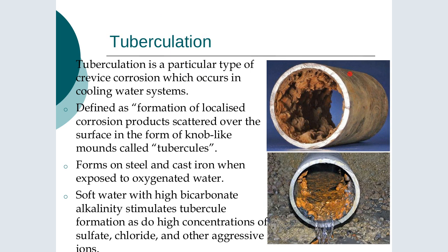So how do we detect that? Well, in this case, by putting pressure sensors regularly on the line, you'll see a change in the pressure occurring over time. And that will indicate that there is a blockage forming, or you may be able to detect it in your pump and then try to troubleshoot down through the system to see where the issue is. Okay, so again, this is quite insidious. You can't see it from the outside.